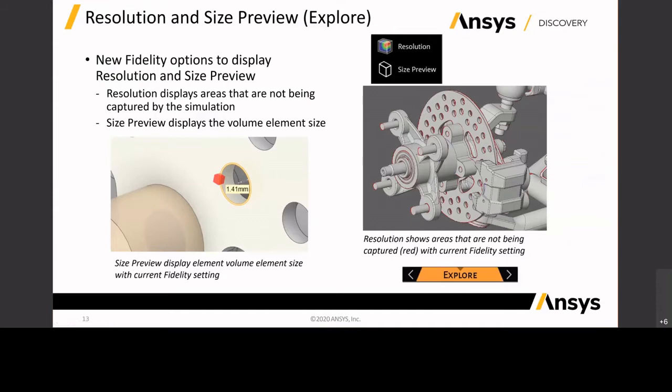In the GPU mode, in the Explore mode, the way it works is it segments the volume basically into voxels of 3D cubes, and the granularity of the calculation is dependent on the voxel size. Voxel size is defined or influenced by the amount of GPU video RAM you have and the number of cores. And that voxel size really gives you that understanding as to whether your simulation is going to be captured at a fine detail.